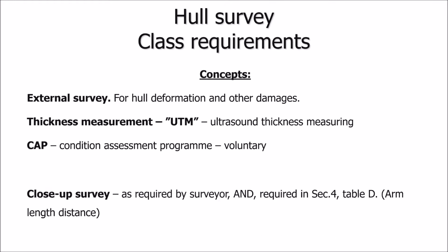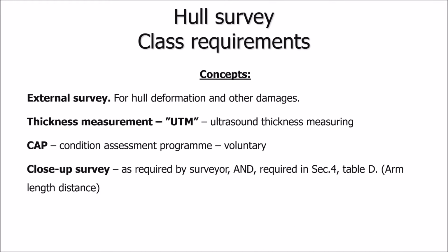And close-up survey, as it is required by surveyor and in regulations here. That is, if you will look a little extra in certain areas of the hull structure at the welding connections and such, where it is more probable with damages like cracks.